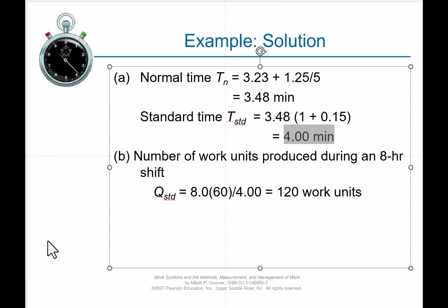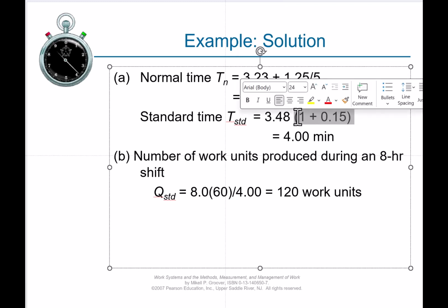All right, guys, so in this case, you learned how to use the normal time, how to use the regular cycles and the irregular cycles here. You learned how to apply the allowance, adding an allowance of 15% to calculate the total standard time.